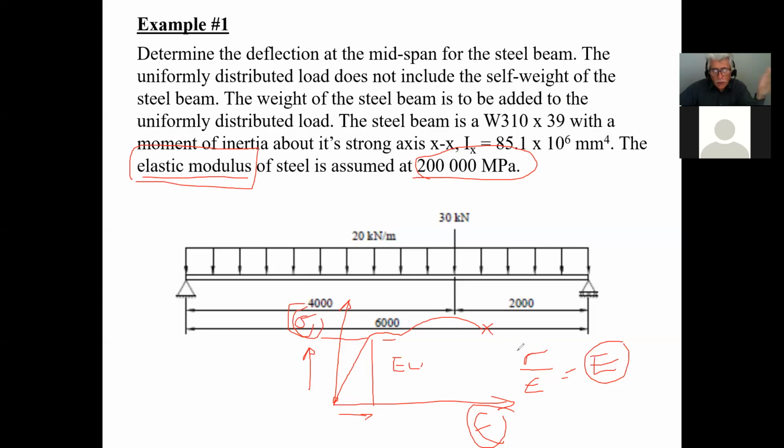And then up to the yield point here, okay, this is called the yield point. The stress-strain, well, you consider it to be elastic. So this is the elastic range of the material. Then after that, it starts getting to what we call the plastic range, where it's going to deform. If you take off the load, part of that deformation is going to stay and become a residual deformation in your member. And then after that, if you keep straining it to the point that you get here, well, it's going to break. Okay, so this is called the elastic range here, and this is called the plastic range.